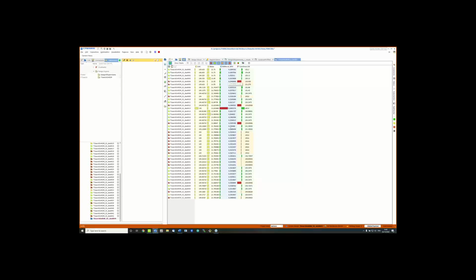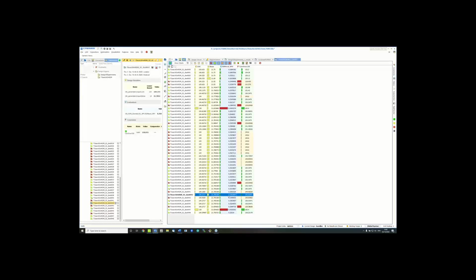And you can also see that the NPV value decreases. And in fact, after those 50 designs are completed, we can find that already after 42 variants, we find this optimized design here, which supposedly, that's what the model suggests, has an NPV optimal value of just 0.25, which would be 4% better than where we started at. And in fact, if we run this very design through CADMATIC again to verify if this is right and if this variant is actually optimal or better than what we had before, we find that those 4% improvement can be validated.